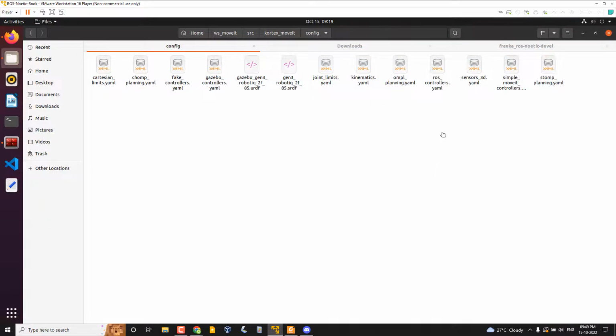You just have to edit it. As I mentioned, MoveIt is a ROS controller client. The ROS controllers work using ROS actions, so the trajectory generated from MoveIt is sent to Gazebo, and the ROS controller server is running on Gazebo.